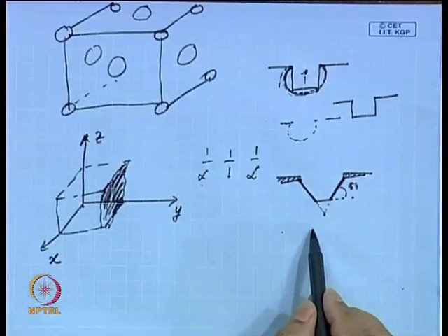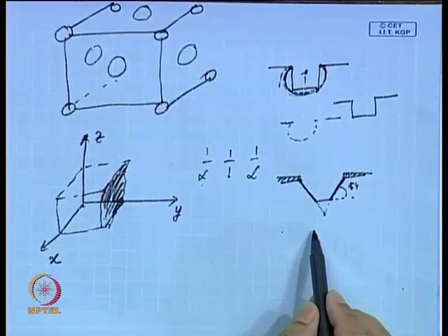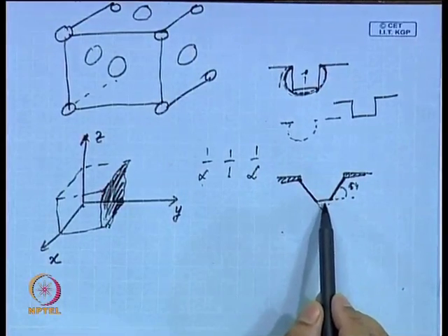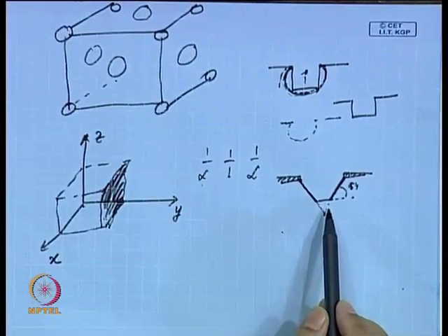So, suppose you want to make a deep channel, or if you want to make a through hole, okay, so you have to be careful. I mean, there is a limit there. Up to certain point you can do, beyond certain depth probably you cannot. Okay. So, this point is there. However, in many situations you want the channel to be this way, and then this anisotropic etching is perfect.